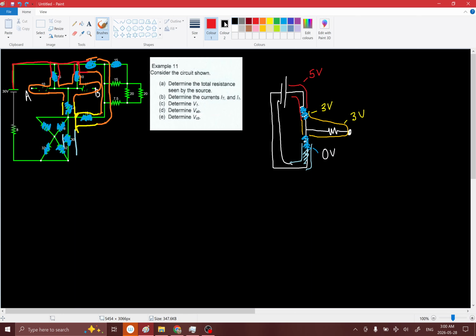So let's label these. This 30 volts is the red water here, and I didn't do the math, but let's just assume that this is going to be 15 volts over here. So this is 15 volts. And then maybe down here, this yellow section would be like 10 volts, something like that. So anyway, the question was, what is the voltage difference between point A and point B? Well, the voltage difference is VA minus VB, and we know that they're both at 15 volts. And so it's 0.